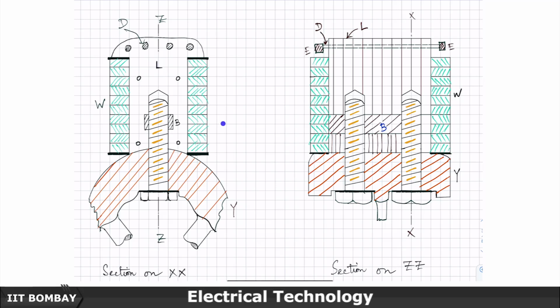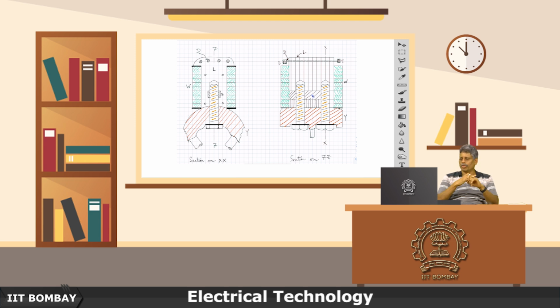So, this more or less tells you what I have explained now: cylindrical rotor and salient pole constructions, and why thermal machines, usually turbo alternators, are 2 pole, while hydro machines, hydro alternators, are usually many poles more.